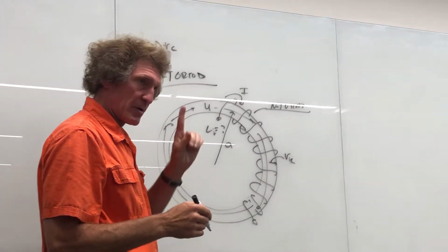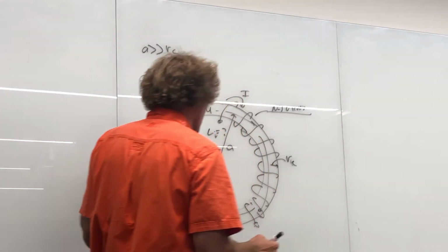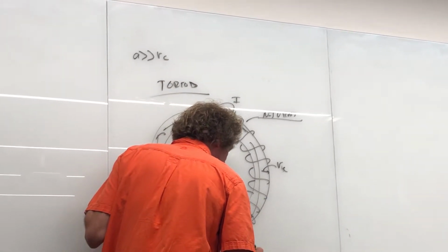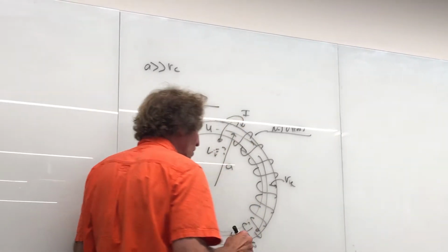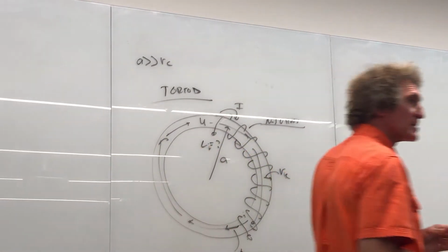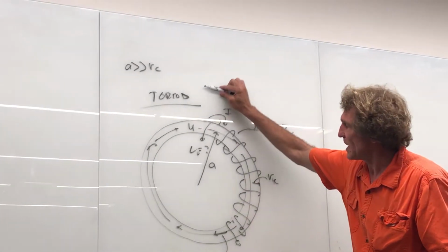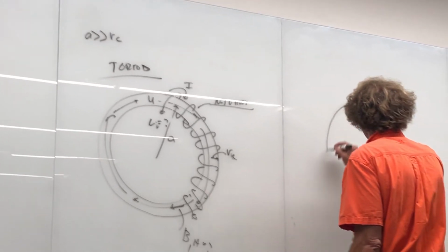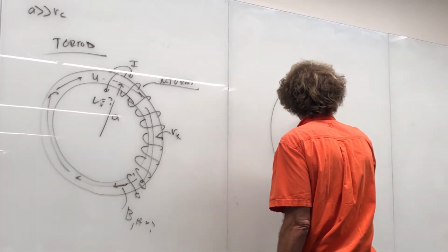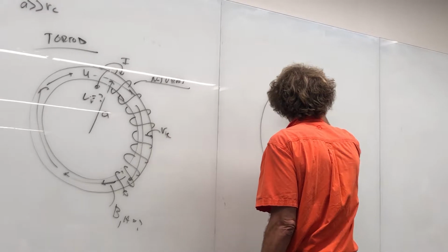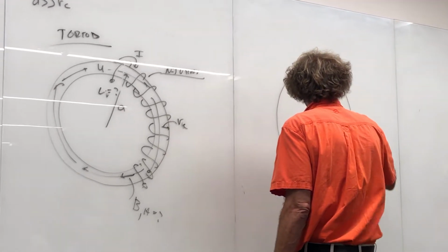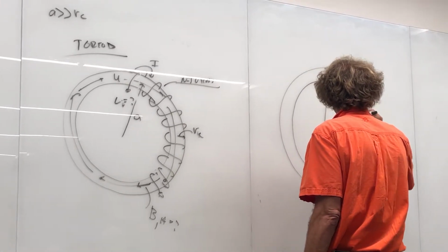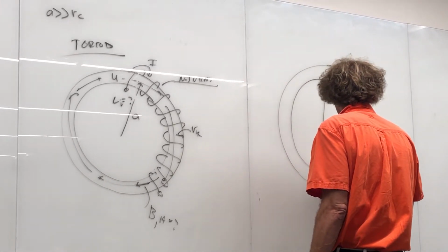So the first step is to find the B field or H field inside of here. So I'm looking for B or H inside that core. Now, remember when we did this last time, I told you the way to think about it is just cut the thing right in half, right? If you cut it in half, it looks like this. You have the mean radius is A, and then you have a whole bunch of turns here. This is cutting it right in half.